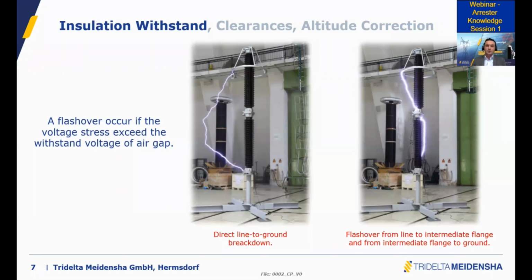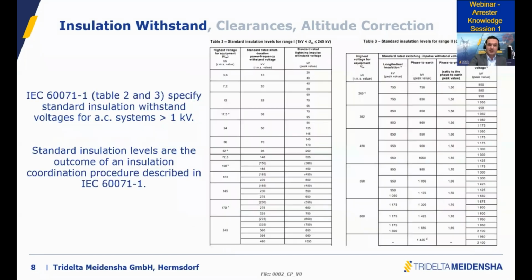It's important to keep in mind for the next slides that when you do such tests, according to clause 8.2 of the IEC 60099-4, we always perform the test on the housing. We never use a complete surge arrester with metal oxide varistors. Otherwise, this will never flash over. So this is a good example to explain the topic of the residual voltage.